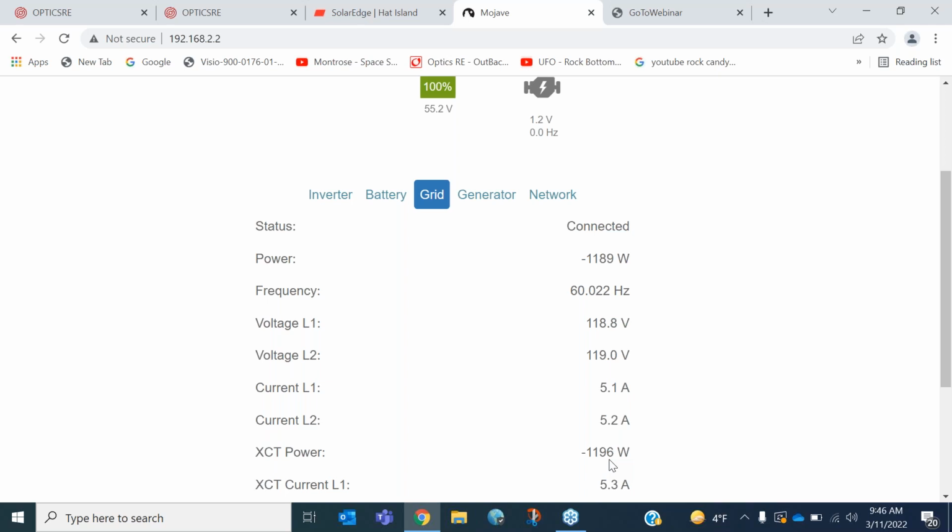If you're using our lithium battery, it does percent of SOC. Minimum SOC is where it'll allow it to go down to, and this is to protect your battery. You say, I want to use my battery during these times or down to this level. And once it hits that level, it says, okay, something has to give. Your battery is low, so we'll let it come from the grid.